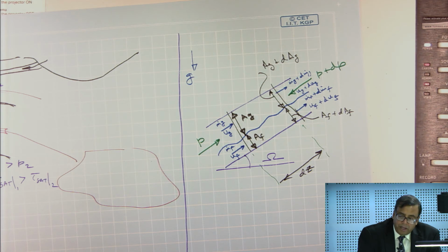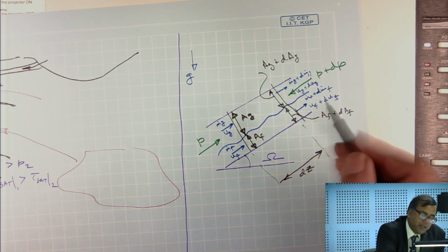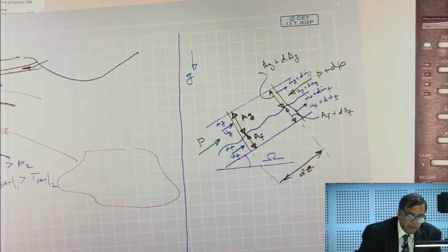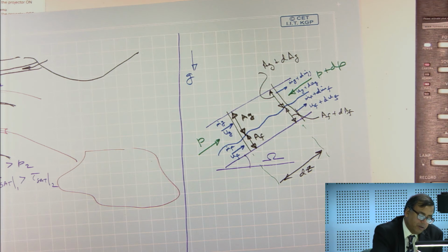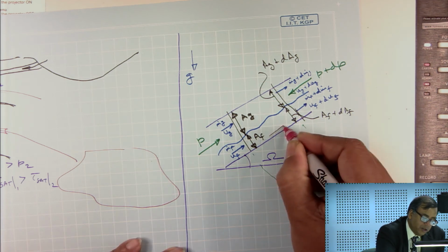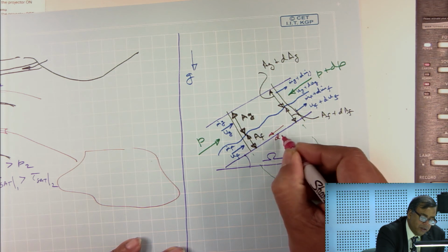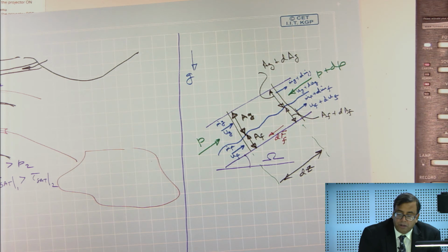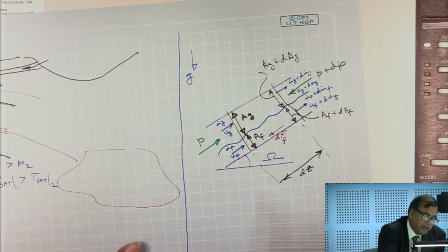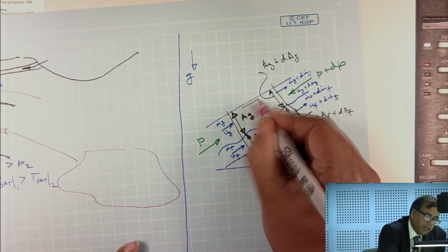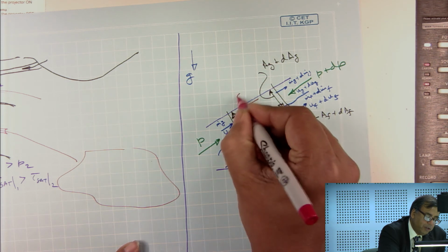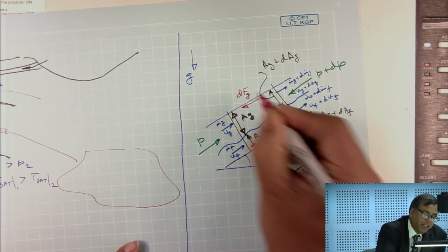On the wall, right. So, let us say because the flow is in this direction, so I expect a shear force in the liquid phase to be in the opposite direction on the wall. So, this is the shear force at the wall from the fluid side, liquid side, and then I will have a shear force on the wall from the gas side. Anything else?